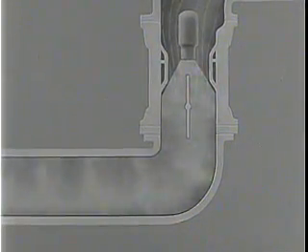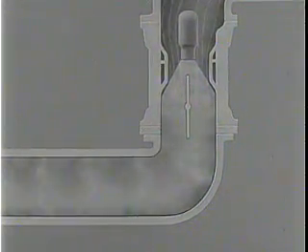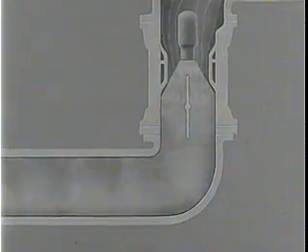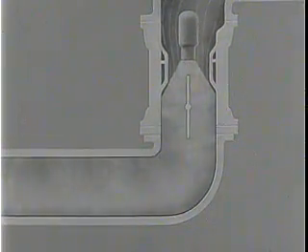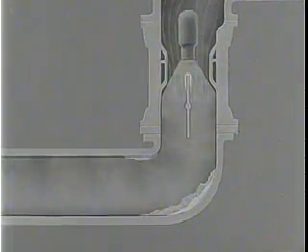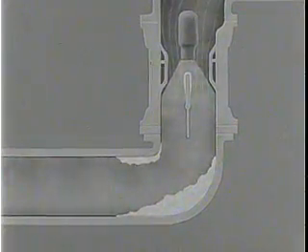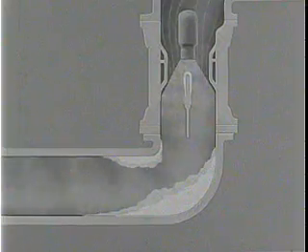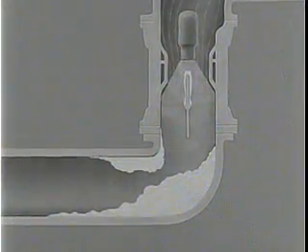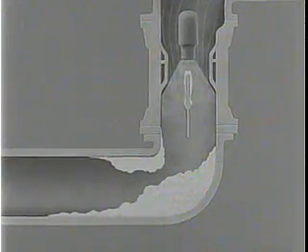As the air flows swiftly into the carburetor, the cooling effects of fuel vaporization and air expansion in the venturi reduce the temperature sufficiently to cause the moisture in the air to freeze on the interior surfaces. Carburetor ice has the same effect as gradually closing the throttle. It does not cause rough engine operation, but as the ice slowly constricts the air passage, it does result in an even loss of power and, in turn, a drop in airspeed.